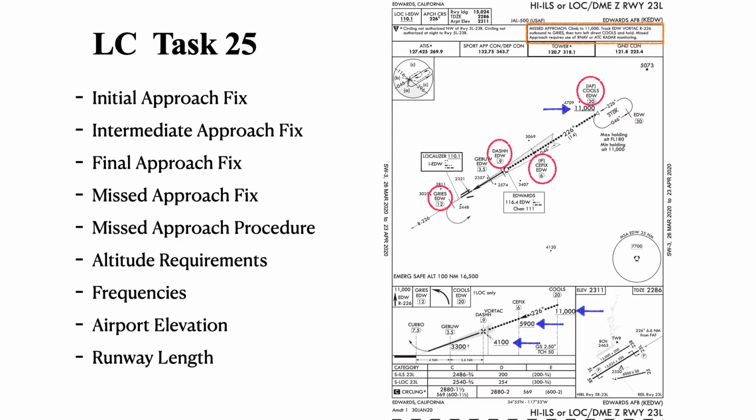It's important to note that if an aircraft at Edwards is going to conduct a south reentry, and you notice that as they get abeam lake bed runway 30 left, or somewhere in mid-lake bed, they start to descend to 4,100 and are maintaining that altitude, then if they have not requested so already, their plan is to go out to the TACAN and go over Dash and fly the practice instrument approach for runway 23 left. And they're going to intersect Dash at or above 4,100. So it's a good indication for us if we notice them at that altitude that either they should request it or we need to prompt and ask the question, are you going out to the TACAN? Because they should have let us know already, but that's probably their intention.